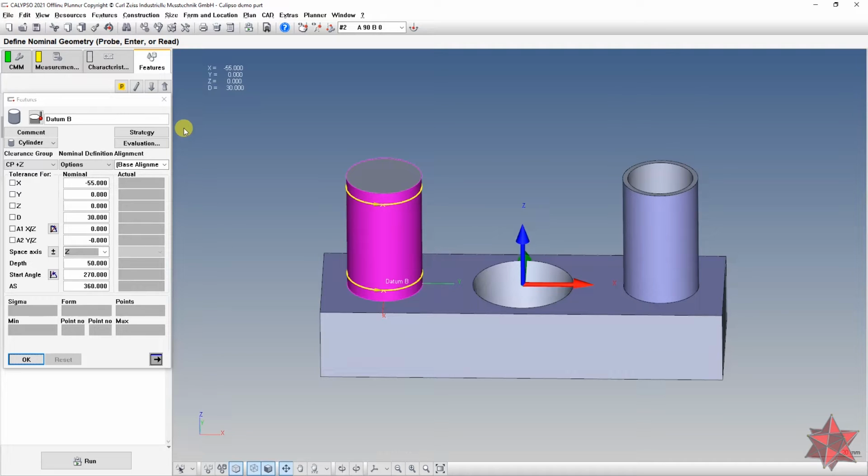The process control check requires a robust, stable, outlier independent, and repeatable result. A typical use of a process check may be to show possible manufacturing deviation, such as worn tools, clamping error, location error, and so on. The results report information about the relative deviations of the workpiece during serial production.